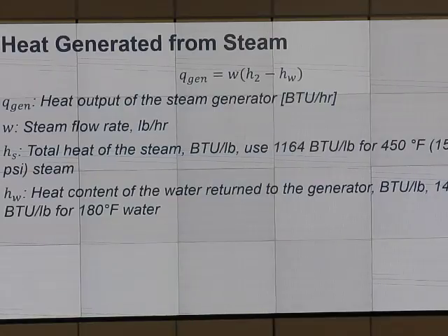If you can do it with the direct method, do the direct method. If you cannot because the fluid is corrosive, then we have to use this. If it is not corrosive, don't do anything in the gun barrel, just use the heater treater. But if it is corrosive, then you may do this to have a lot of retention time and more heat for the separation.